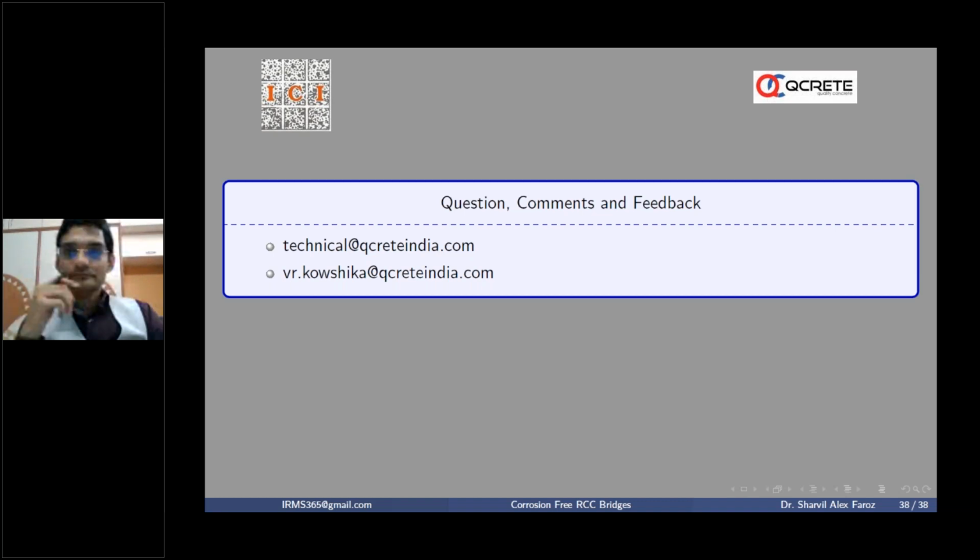Yeah. Okay. First question. The diffusion coefficient is not constant value. It varies with time due to the pozzolanic reaction of the supplementary cementitious materials. Hence, may I know at what age of concrete you are considering the D value? It is asked by Dr. B. Kameshwar Rao.